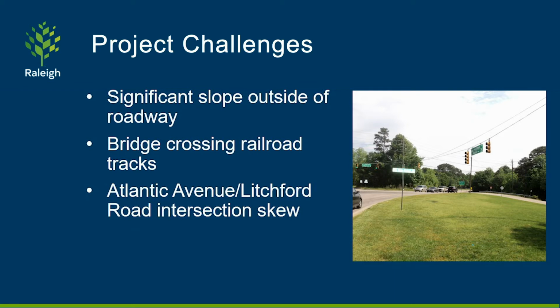The alignment of the intersection at Atlantic Avenue and Litchford Road has a significant skew. This skew contributes to the high number of crashes at the intersection. During design, options were explored to remove the skew and create a perpendicular intersection. Due to the impacts to adjacent property, these options were not considered. However, the skew of the intersection was reduced to the extent possible to improve safety through the intersection. Additionally, a dedicated right turn lane onto Litchford Road will improve the flow for through and left turning movements.